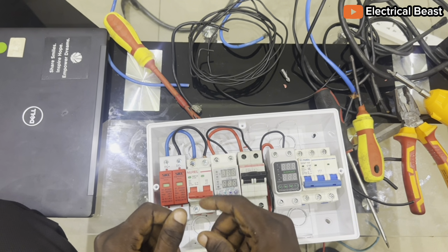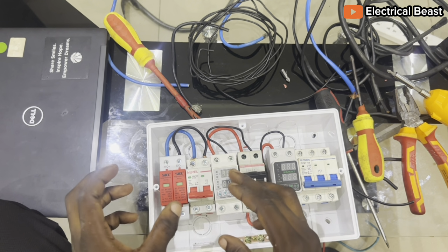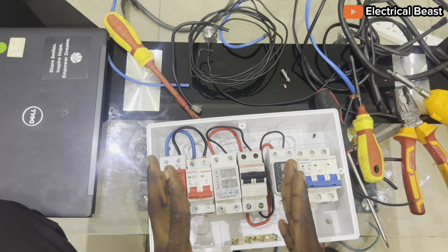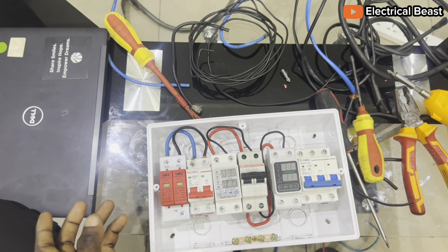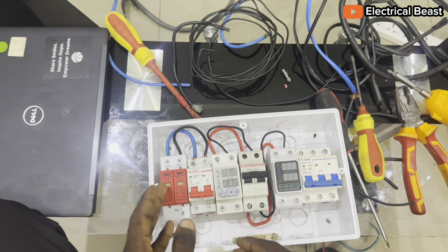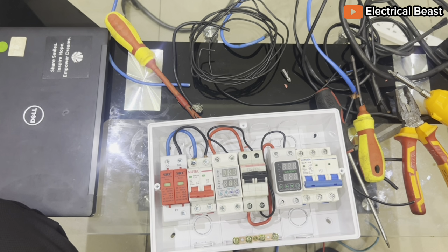So you connect an earth bar, a bus bar, connect everything together on the metal, then put the earth rod on the ground. Then make sure the resistance at that place is low so that current can flow into it from any point, whether from the AC surge or the DC surge or from the inverter, wherever the surge current, leakage current or fault current is coming from, it can flow to the earth terminal directly.